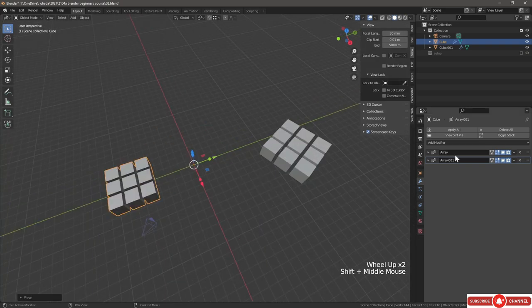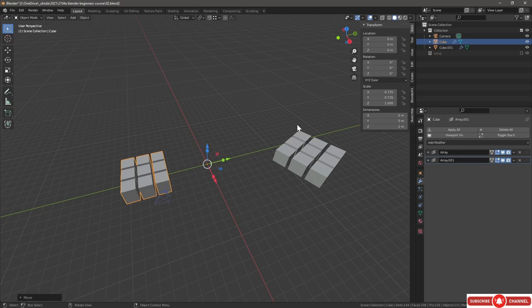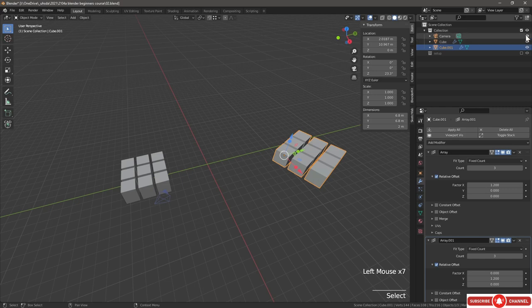Okay, so moving on, let's talk about the outliner, which is over here. That contains all the objects that we have in our scene. We can click and select items directly within the outliner. And as you can see here, we have a little eye icon, and we can hide things. But it's a little bit deceptive because even though we're hiding it in the viewport, this will still render out.